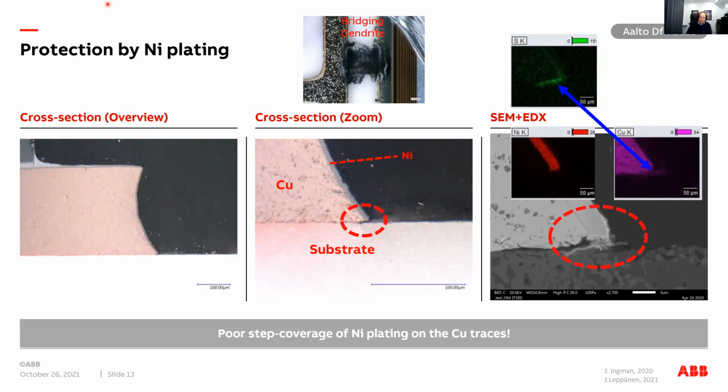As far as I have understood, typically it takes a little bit longer for the epoxies to pass the moisture, but definitely they will also transfer the moisture through eventually. And we can see this in humidity tests also. So there, the chips need to be robust enough to protect themselves. You cannot use the epoxy as any kind of protection there against the moisture.